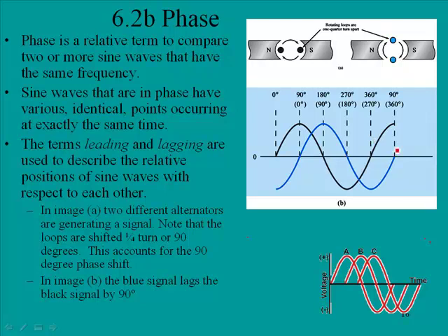Remember, let's pretend that this is our 60 hertz signal, and remember that the time of the 60 hertz signal, we said, was 16.66 milliseconds. And if that is the case, then we can look at the time from here to here as well. And so that is 1/4 of the signal, and that's going to be about 4.167 milliseconds.